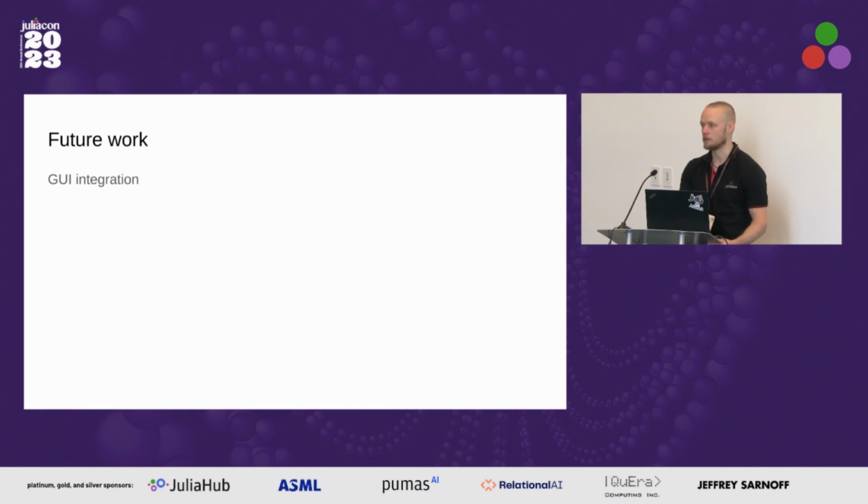So the actual linearization, we used forward diff there because it's simple. You can switch it out for the symbolic linearization, because sometimes for small models that gives you some insight if you have linearized the nonlinear system symbolically. But there is nothing preventing you from doing any other linearization. And if you have a model that has sort of a block diagonal structure where some blocks can linearize symbolically, other blocks can't, you're kind of stuck and you have to linearize the whole thing. We don't have any special case to handle that.